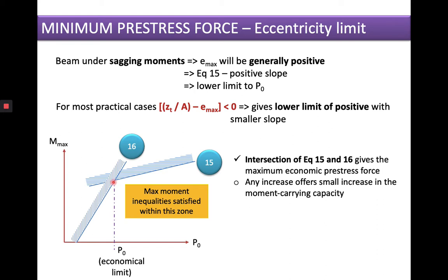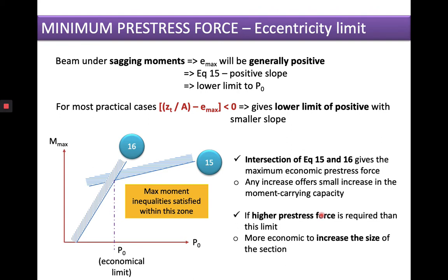It is most economical if we are providing the pre-stress force only up to this point. If we are requiring higher pre-stress force, which is higher here, we can see that the moment maximum will not move much.